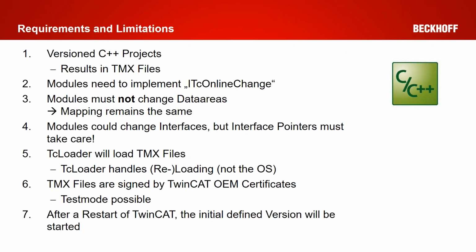TMX files are signed by a certificate comparable to the operating system certificates, which you know from the 64-bit operating systems, but we are providing such OEM certificates, and we'll have a look into that in a couple of minutes. For sure, the test mode of the operating system is again available for the TMX files. So you could directly start development and investigations after the webinar without any interactions to Beckhoff or any third party.